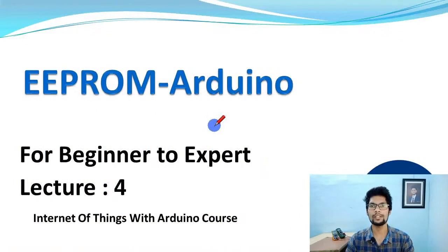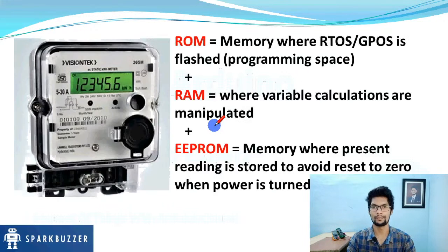Guys, in this tutorial we will learn EEPROM with Arduino. Let me tell you the best application of EEPROM: your home energy meter, or what you can say power meter. It has EEPROM. Why? Even if electricity is cut off, your previous reading is stored in the EEPROM and later displayed on the LCD when power is turned on. So this is one application where EEPROM is used.